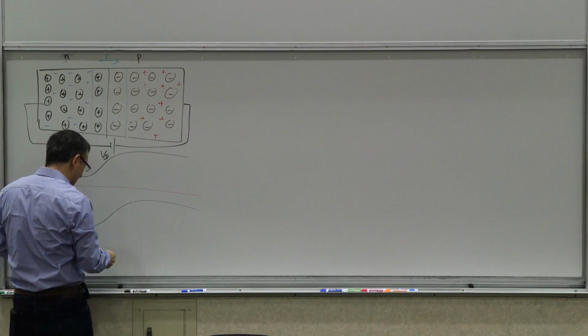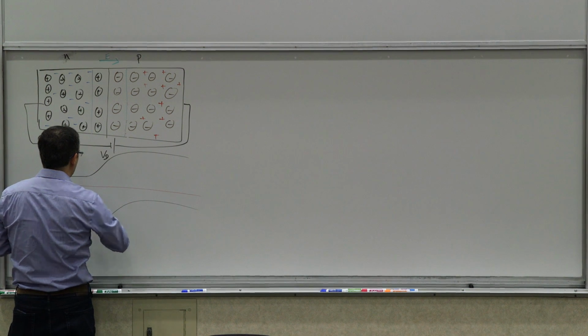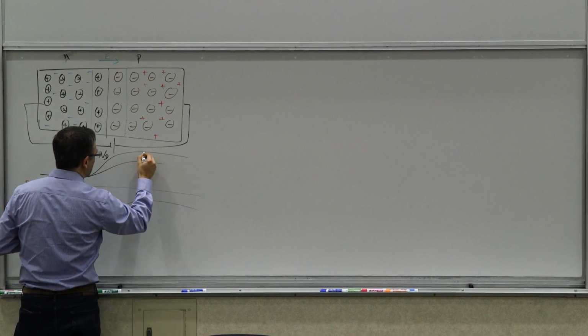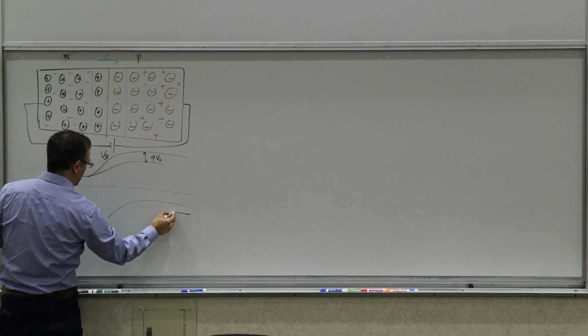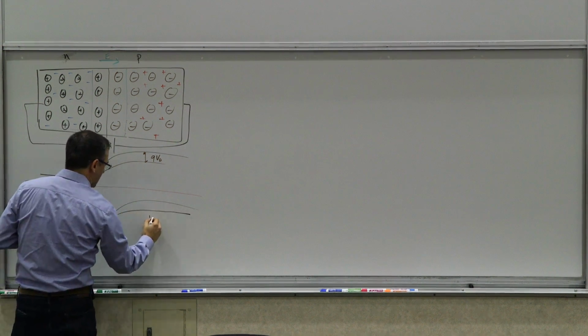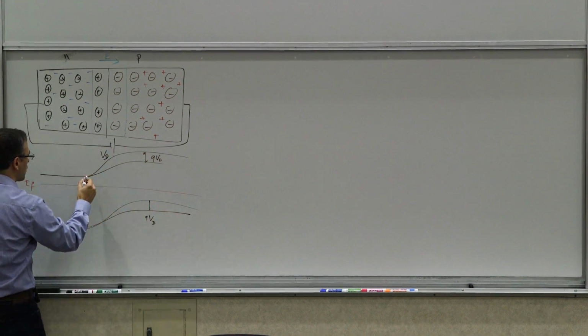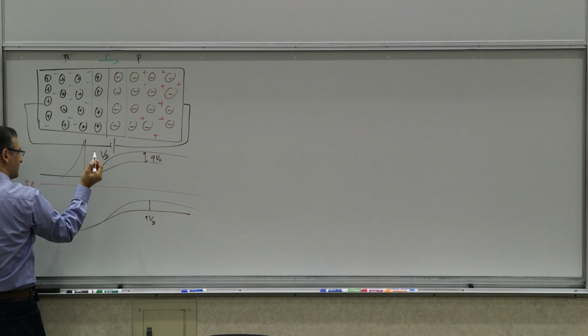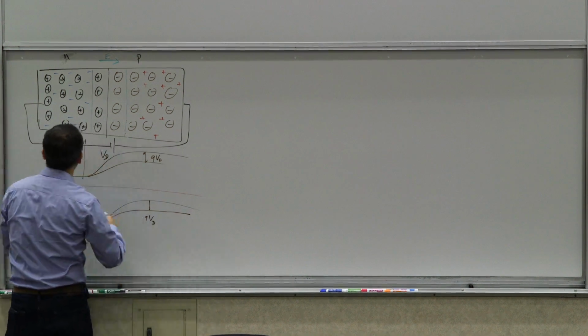So what happens is that when you apply a voltage like that, you're lowering this potential barrier by VD, by qVD really, and you're lowering it here the same amount. So now you have really a Fermi-Dirac distribution, but it's approximated as a Boltzmann distribution of electrons.